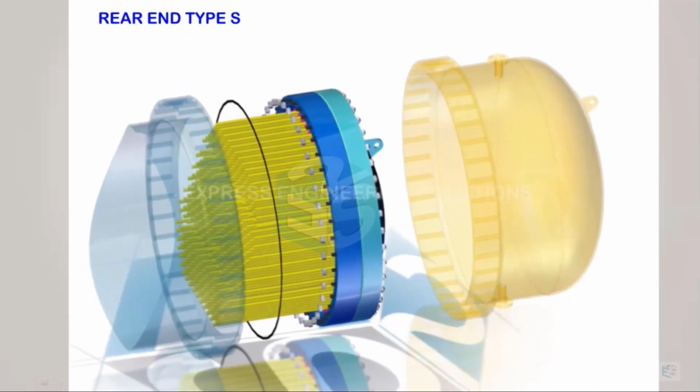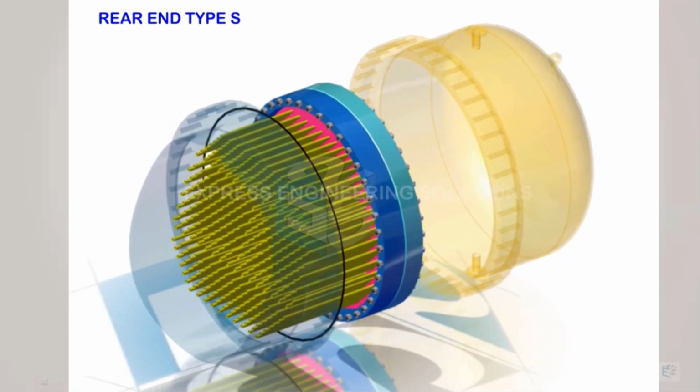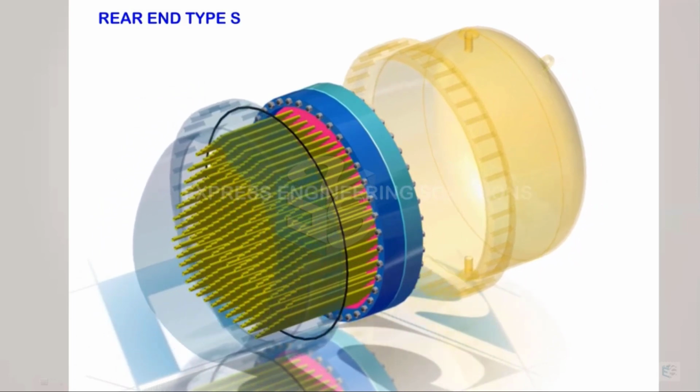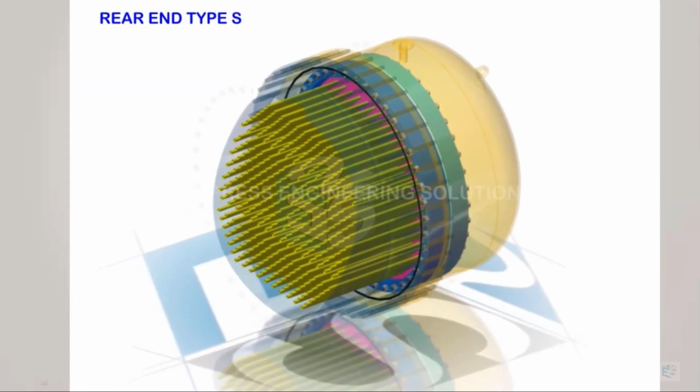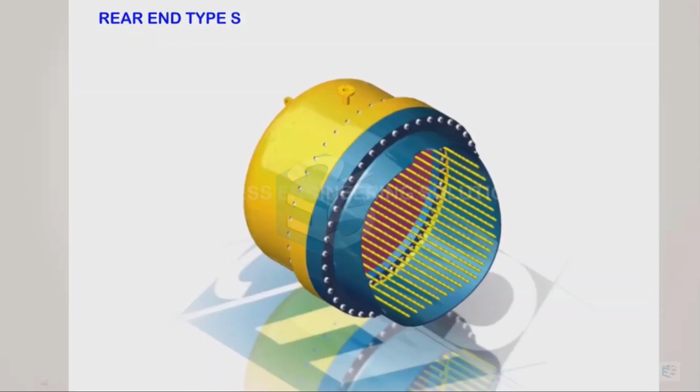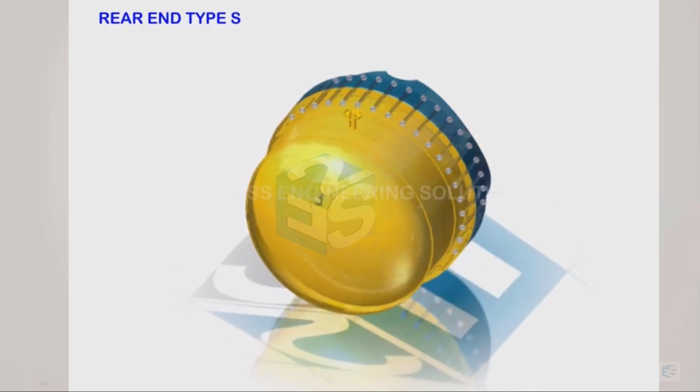And when we tighten the bolts, the gasket will be compressed. So that represents your floating head assembly. It comprises the tube sheet, split ring, floating head and gasket along with the tubes. And after that, the shell will be inserted, and from the other side the shell cover will be inserted, which will have a higher diameter than the OD of the head flange and the split ring flange. So that backing device is provided. That's the reason it is also called a floating head with backing device.